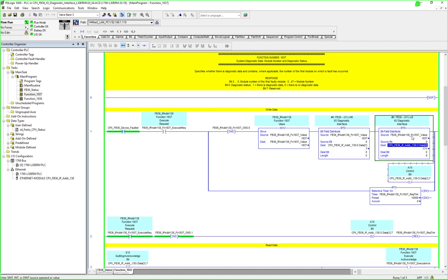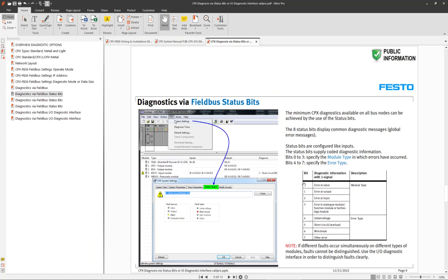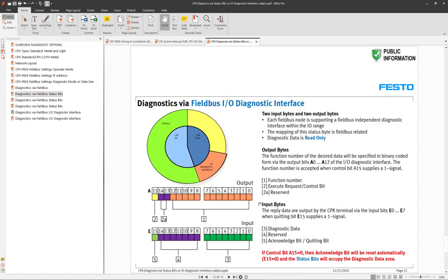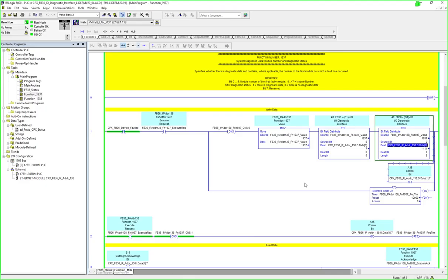Okay, this is basically a bit distribute, and I'm basically taking a portion of this value, which is the 16-bit number, and I'm putting it into the raw data area here. So I'm basically shoving it, the whole value, I'm taking part of the integer and putting it into this first output byte, and then the next part I'm going to take and only put these 5 bits in. Okay, that's what this does, this and this and this.